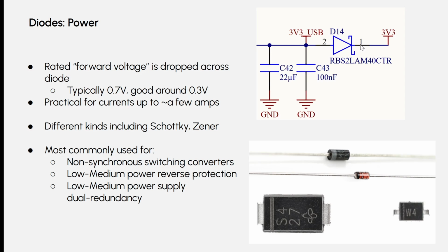Because diodes only allow current in one way, what this effectively means is that when the 3.3 volt supply for the whole system is usually on, there's no problem. This diode will not conduct any current and it will not turn on. It just chills there. But if the other parts of the system power were shut off, like when you have it on a test bench, not hooked up to everything else, this diode would allow current flow because there would be no source here, and you would get about 3 volts here because you would have 3.3 minus 0.3. So you don't have to study this exhaustively, but this is just an example of where a diode is very useful, a power diode specifically.